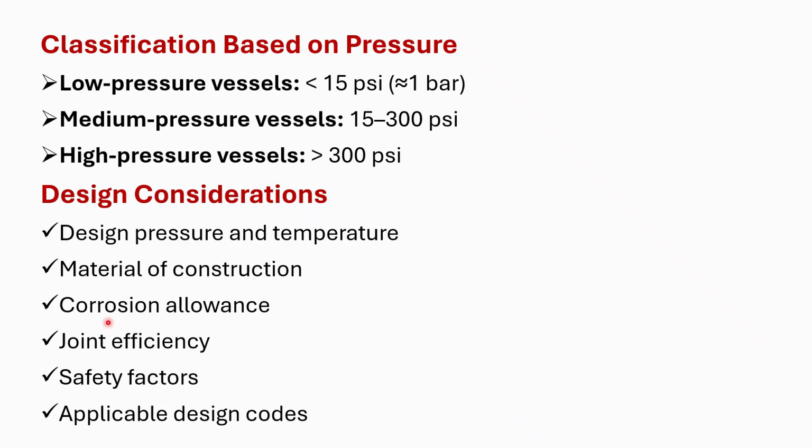Similarly, we can go for J equal to 0.85 for spot welding kind of joints, where the factor of safety is 85%. Similarly, it can be still lower for room temperature operated vessels, where the leakage can be easily detected and leakage does not affect the operation parameters of the process. Then you can have normal joints where the efficiency has to be rechecked and reconfirmed.